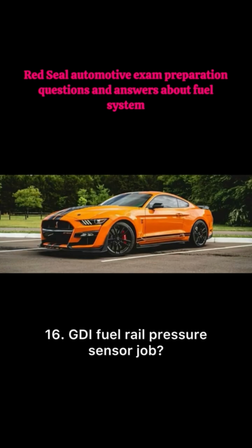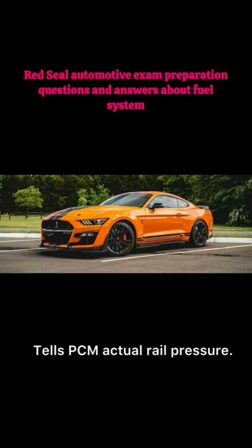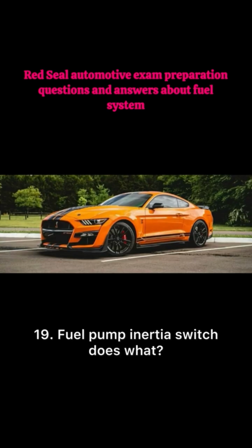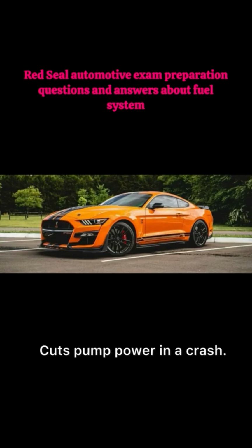16. GDI fuel rail pressure sensor job. Tells PCM actual rail pressure. 17. P0191 code. Fuel rail pressure sensor issue. 18. TBI uses what injector type? Low pressure, high flow injector in throttle body. 19. Fuel pump inertia switch does what? Cuts pump power in a crash.